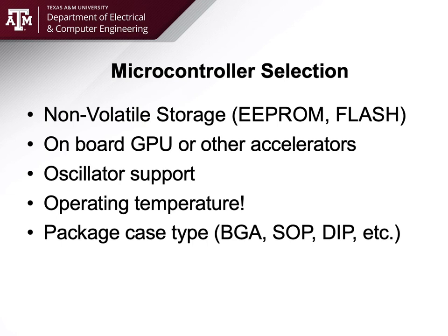So you're going to have things like flash and EEPROMs that are going to hold your calibration constants, specifically EEPROM, electrically erasable programmable read-only memory. This is primarily going to be for your calibration constants. How many ADC counts versus temperature? 212 degrees Fahrenheit, boiling, is 2,222 A to D converter counts, something like that. You have a calibration curve in memory or different settings. The set point for this PID algorithm to control this heater is 80 degrees Celsius. Well, that would go in your EEPROM.